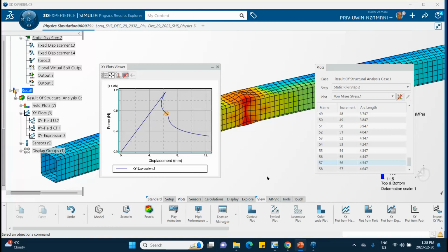We did first the buckling, and then the static step to introduce a deformation, or imperfection, and finally the static Riks. Now remember, there are other ways of introducing deformation or imperfection into the problem, including manual keyword changes and things like that. But here I just apply a sideways force, in this case upward force, and put a dent, basically an initial dent into the tube. That's pretty much it. Good luck.